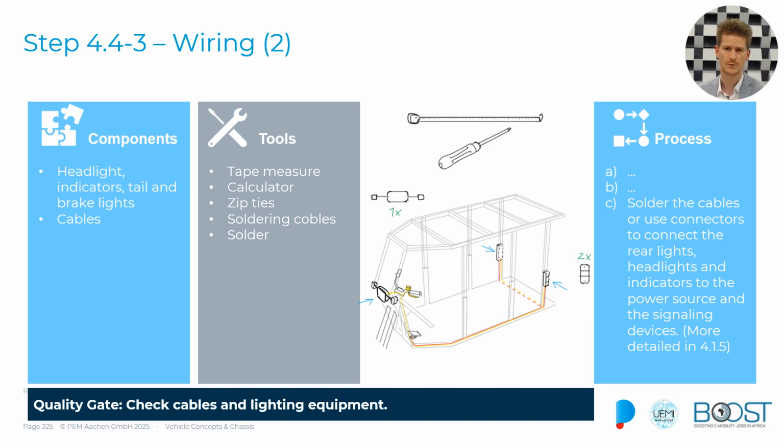And therefore, the last thing is the quality gate. So check all the cables, check that they're tightened up, and check the lighting equipment that it works properly and that it is pointing in the right direction and can be operated without any problem.